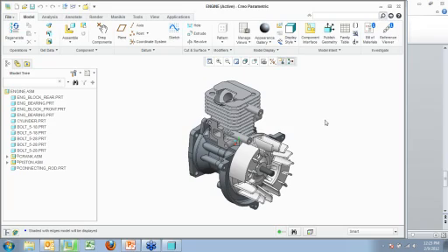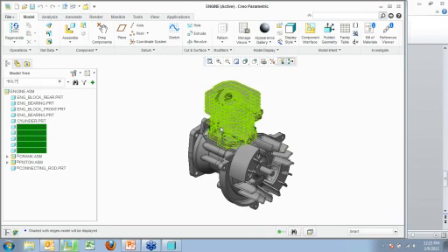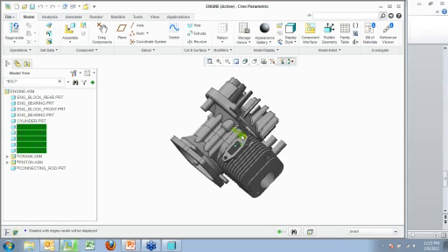So if I'm going to go in, and now I need to find some bolts, one of the things they've added in the model tree is a search bar, where I can go in. If I'm looking for bolts, obviously this is a small part. You can see all of my bolts right there, but let's say this had 100,000 components, then I go in and type star bolt star, and hit enter, and it'll find all of the parts that have bolt in the part name. So you can see my 5 by 18 millimeter bolt, my 5 by 28 millimeter bolt are all highlighted. In the model, it also highlights them in green.